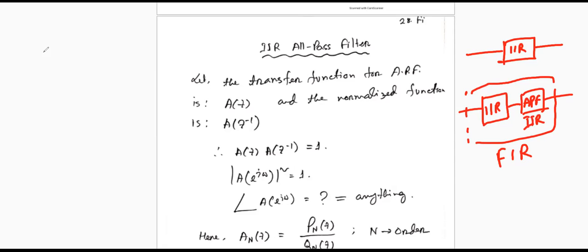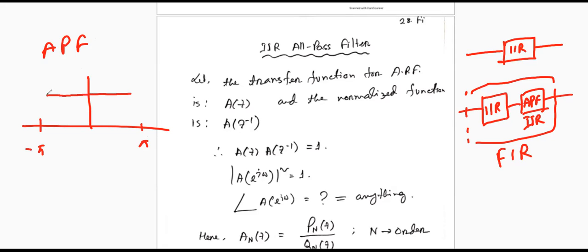One characteristic of the all-pass filter is that it will pass everything. So that means in the frequency domain, if we talk about the frequency domain from -pi to +pi, that is our range of view, it will pass everything. So the magnitude of the all-pass filter is 1. What about the phase response? This is the magnitude response. You can write it this way, H(omega), the magnitude.